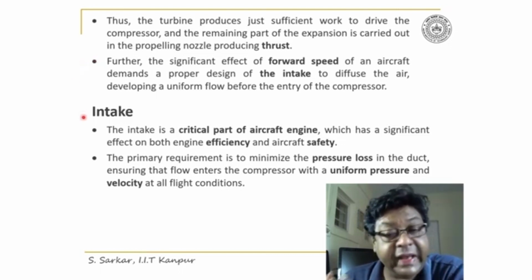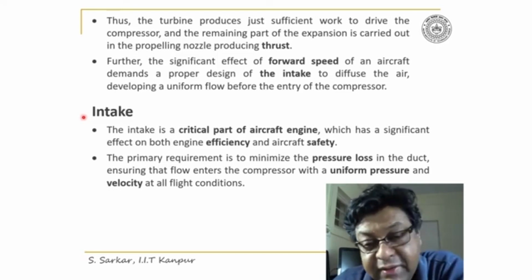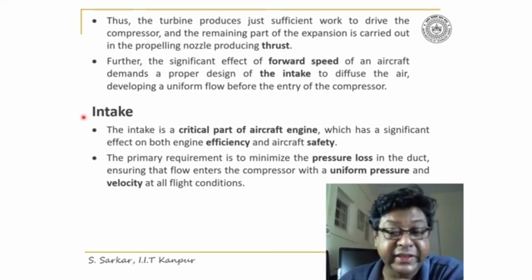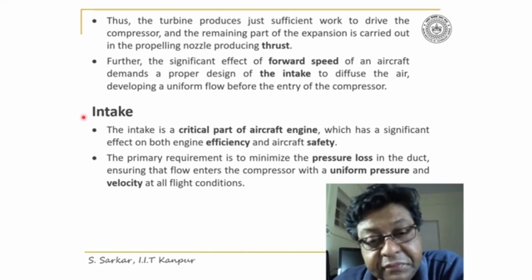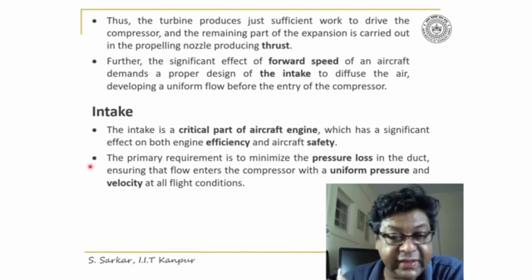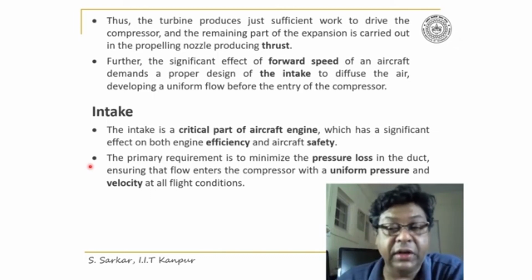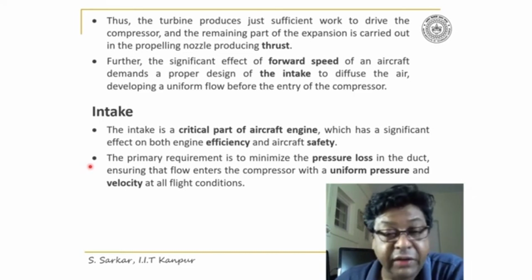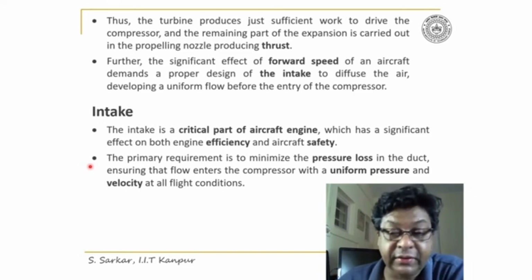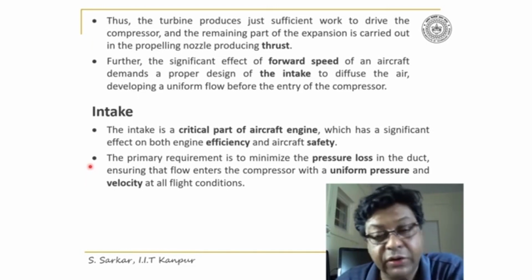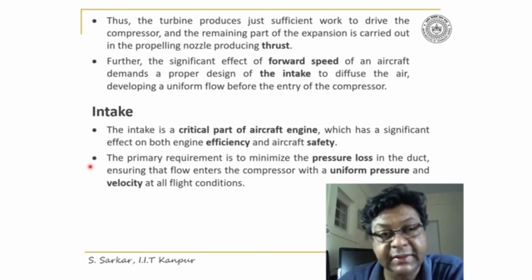The intake design is very critical for the aircraft with respect to its efficiency and safety. The primary requirement of the intake design is to minimize the pressure loss in the duct, ensuring that the flow enters the compressor with a uniform pressure and velocity at all flight conditions.